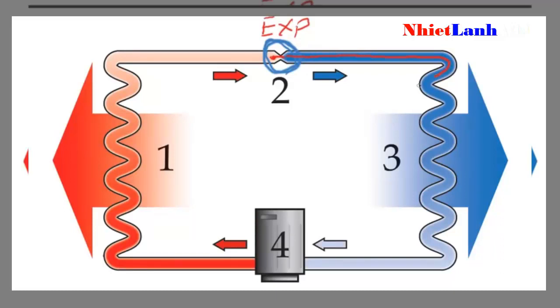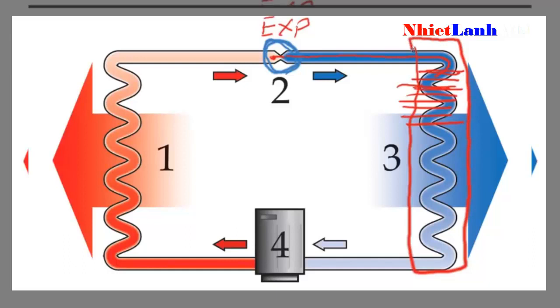Now, the evaporator coil has aluminum fins that are attached to it, and what that does is helps the heat from the inside air that's blowing over this coil to absorb into the copper or the aluminum fins and the copper tube and then into the refrigerant gas. So where the evaporator coil gets its name is this liquid enters the coil and evaporates, and by the time it gets to the end of the coil, it's totally evaporated and there's no liquid left in it, and so we have a gas by the time it reaches the end of the evaporator coil.